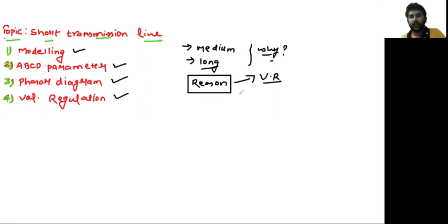Then after that, we can calculate the voltage regulation, and we can try to define some ways to compensate the voltage drops with the help of voltage regulation. So we do modeling to calculate the voltage regulation and to define solutions for low voltage and high voltage at receiving ends. Second thing is to calculate the I square R losses, so we also have to see the ohmic losses. These are a few reasons to keep in mind as to why we are studying transmission line modeling. This is the fundamental.